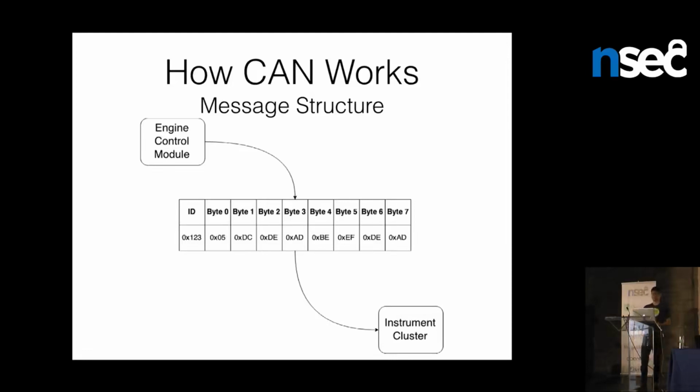So in this case, you have an engine control module that's going to be taking a pedal request, figuring out what to do with your engine and all that stuff, and also sensing everything from oil pressure to intake air pressure, different exhaust stuff. There's just a whole bunch of sensors in an engine. It's nuts. So from that, it's going to periodically just be sending out messages, and they're all broadcasts. So just whoever decides to pick them up gets them.